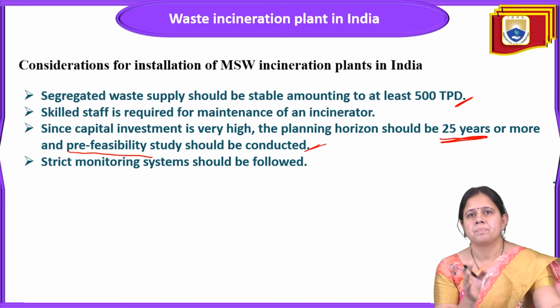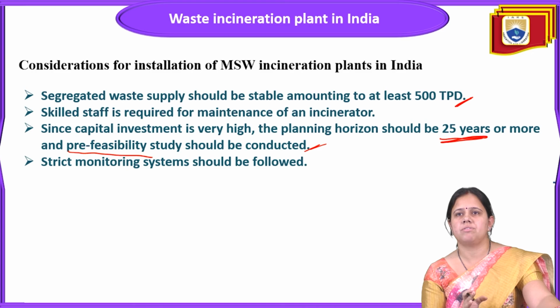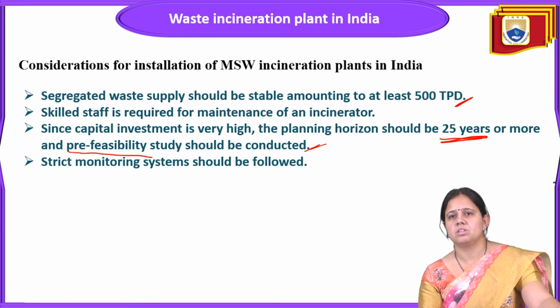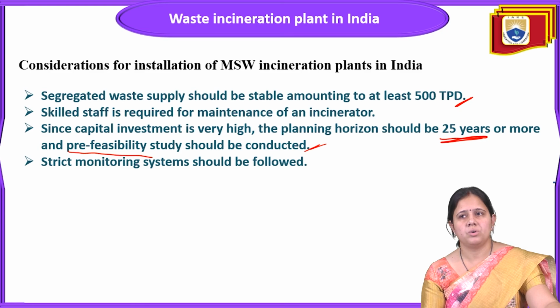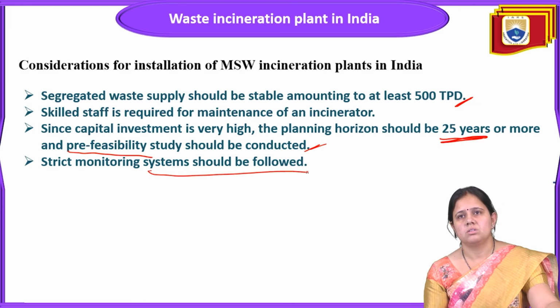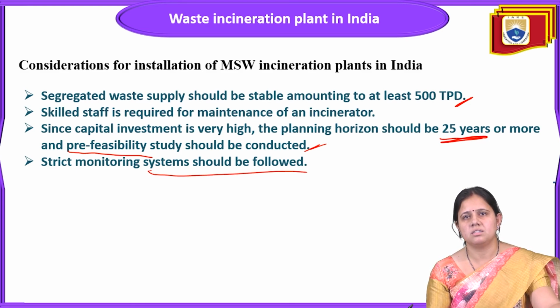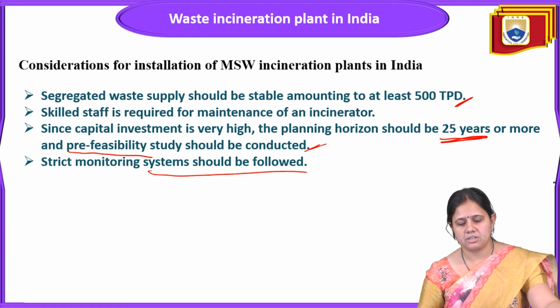So these are some of the considerations for installation of an MSW incinerator plant. The main thing is that the lower calorific value of the fuel should be around 1400, pre-treatment is very much required, and skilled staff is required for maintenance of an incinerator. Since the capital investment is high, the planning horizon should be 25 years or more, a pre-feasibility study should be conducted, and strict monitoring of systems should be followed. These are the important points to keep in mind while designing an incinerator plant.